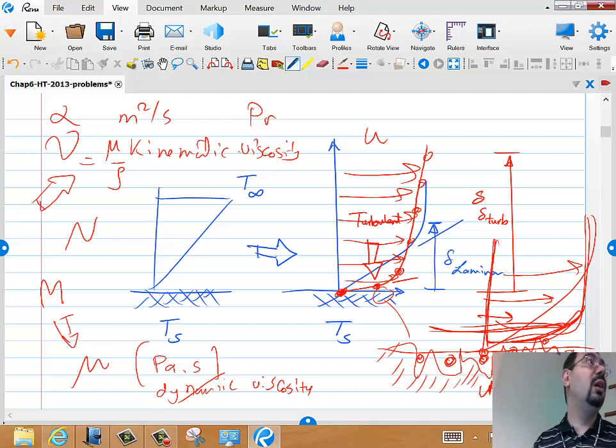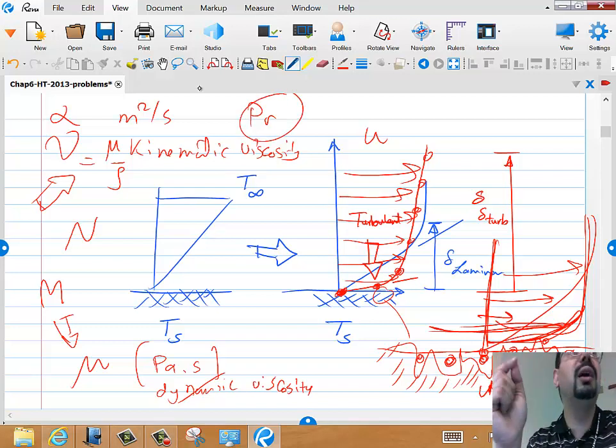If the Prandtl number is really high or very low, that means it has a preference in which of them it diffuses pretty quickly. All right. So for gases, you should expect the Prandtl number to be around 0.7. So that means gases have almost the same alpha and nu. For liquid metals, we will see what the Prandtl number looks like. All right. But keep in mind that the Prandtl number will tell us the ratio between alpha and nu. We'll see the definition in a second.